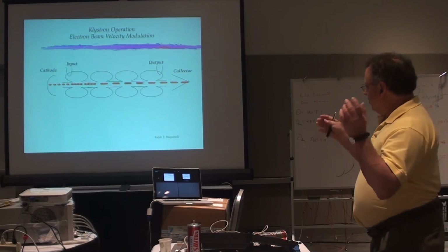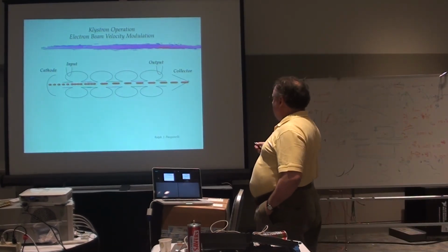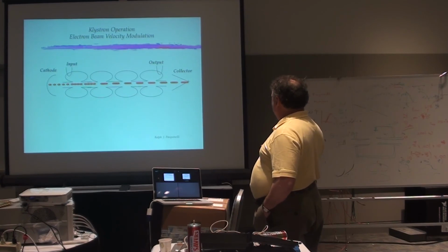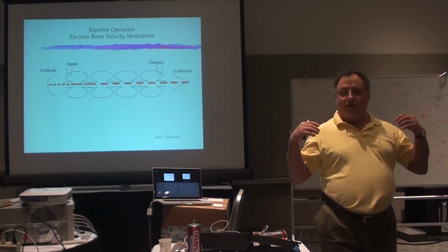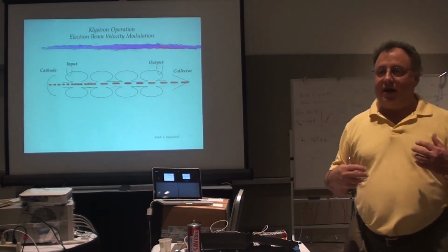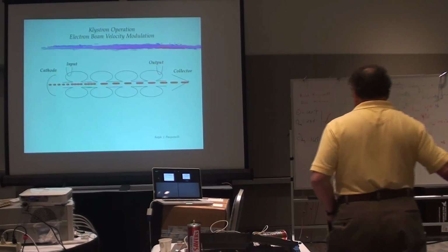So here, the beam is going by, and it's going ping, ping, ping, and if it's designed very well, and getting bunched a bunch more, by the time it gets to the output cavity over here, it's got a nice tight bunching, and it's now putting a huge amount of energy into that final cavity. So you have to adjust this output coupler to take that energy out.